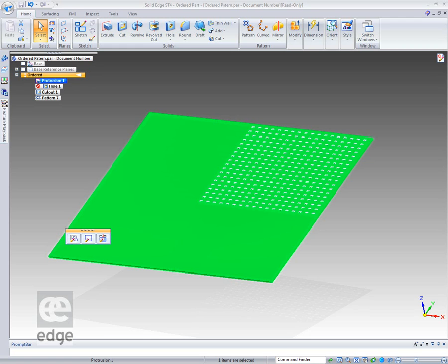If that plate is changing in shape, it's got different levels in it, its topology changes, which is the true term, then you would use smart. Smart can do everything fast can do, but the part files become bigger, they're slower to calculate, and so on. And yes, we can do that in synchronous.